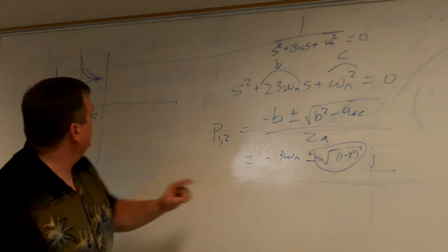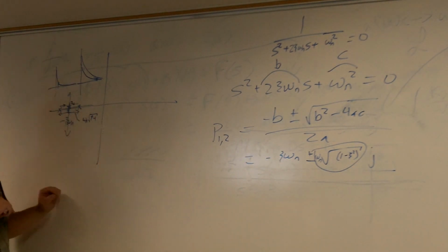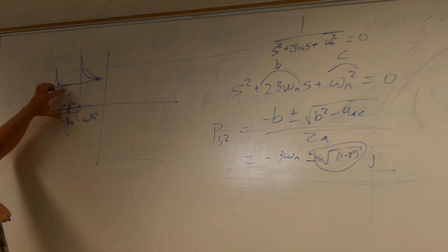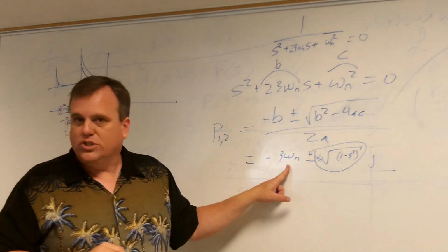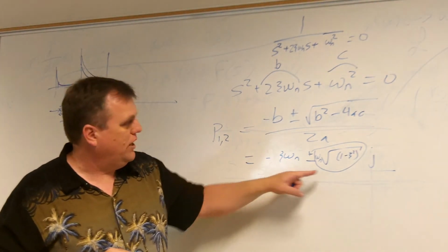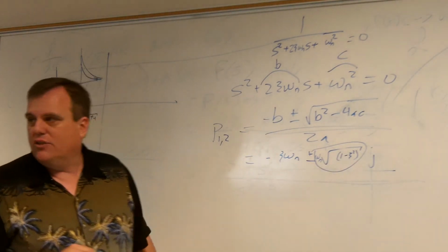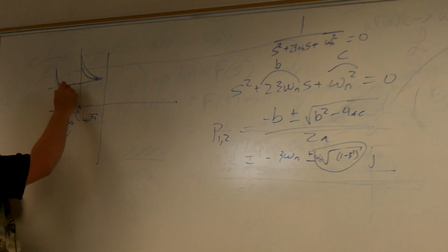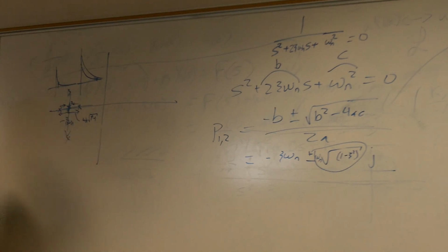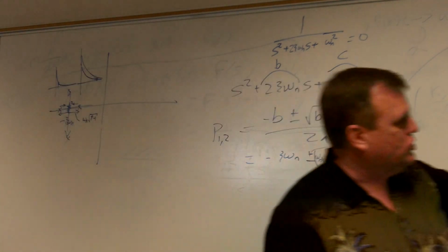And it's plus or minus J, so they move off in pairs. All right, what we call complex conjugate pairs. They're centered right above, that's the real part, which is still giving me that damped area. And this is now telling me what the effective damped frequency is. Because now I've got these two, they're not on the real axis anymore. That corresponds to this response right here.